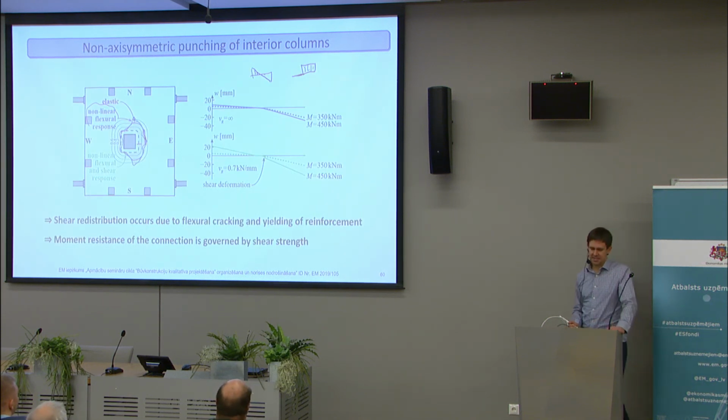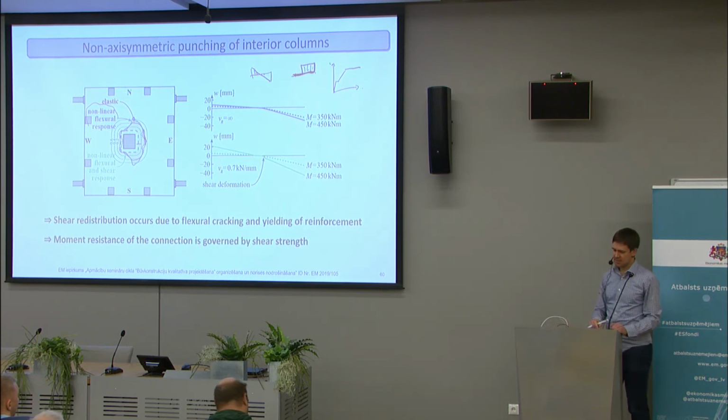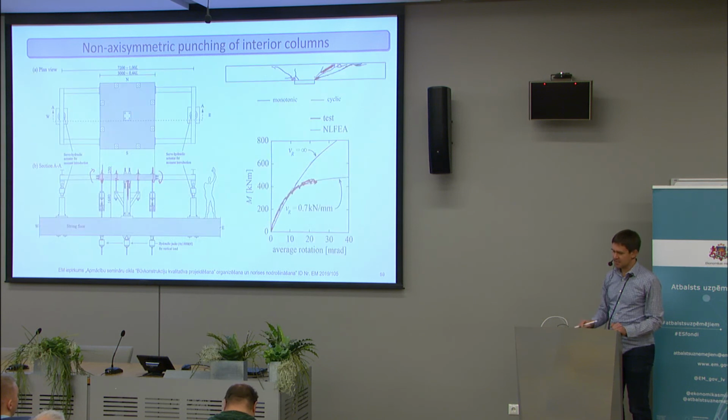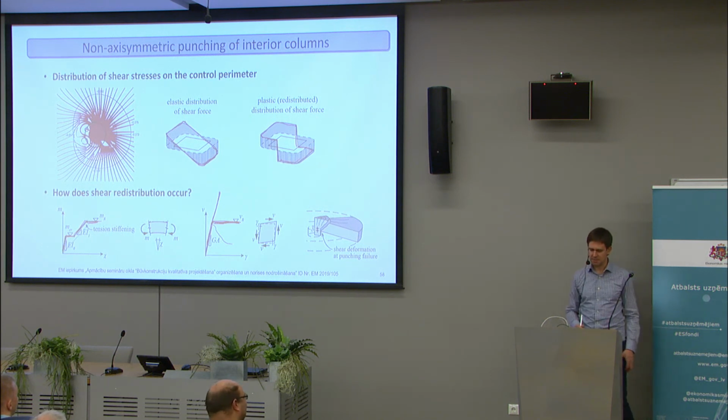So it means that to achieve the shear plastic distribution, it's actually enough to have just non-linearity, or just a plateau, in bending, but not in shear. So we don't have to make the assumption that our shear resistance is somehow ductile in order to have this plastic redistribution like the Eurocode proposes.